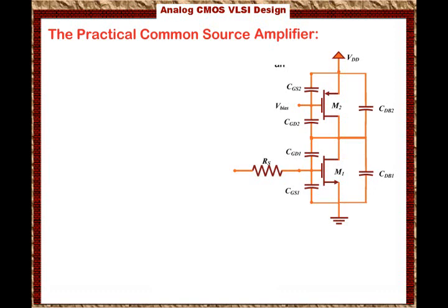As you can see, we have these 6 dominant capacitances, and we can evaluate each of them, as we said earlier, once we have the process parameters and the geometric shape of the transistor. The geometric shape of the transistor is a function of the design. We get the gain of the amplifier by looking at the geometric shape of the transistors, and we get the capacitance values by knowing the geometric shape or size of the transistors. So the geometric size of the transistor determines the gain and the frequency response, because it tells you the magnitude of the capacitances.